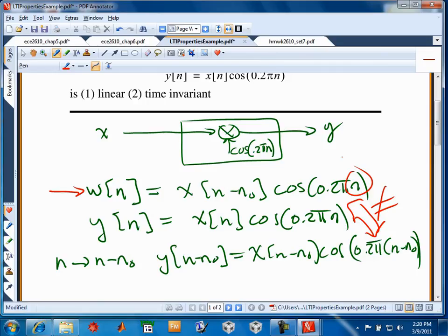It's just doing its thing. This thing right here is a property of the system. If you go ahead and delay or advance the input, the system doesn't care, but it definitely doesn't know about n naught. It's like it's dumb. So don't fall into that trap of thinking that the system time clock gets shifted, because it's just humming along with its own beat, basically, time variable.